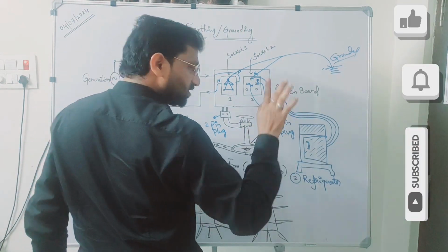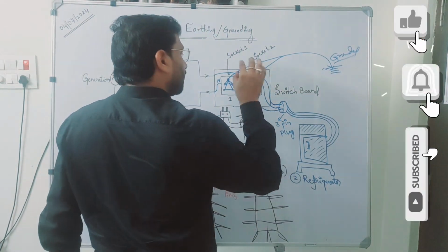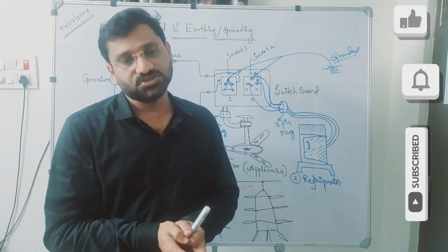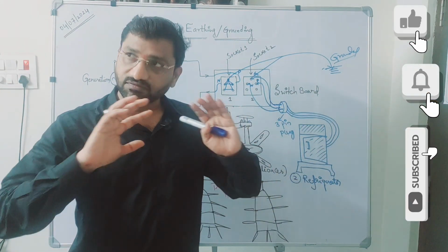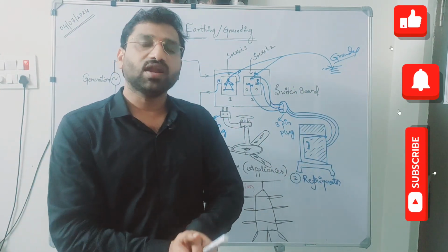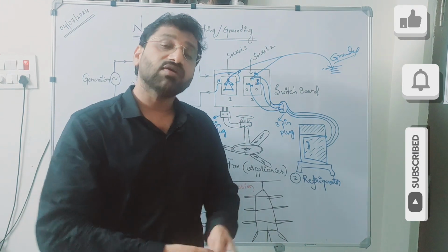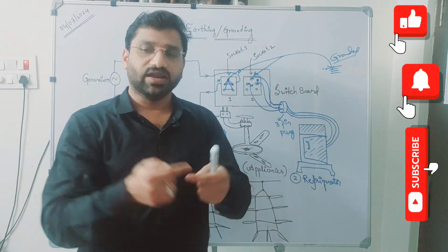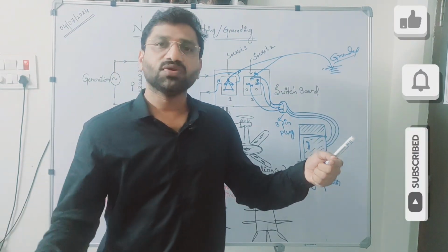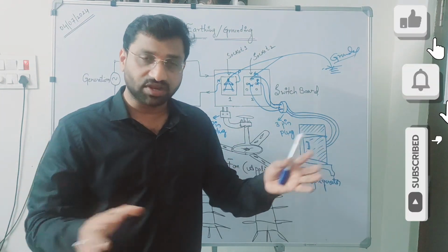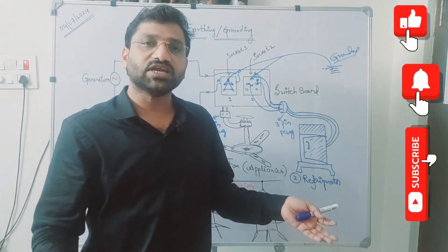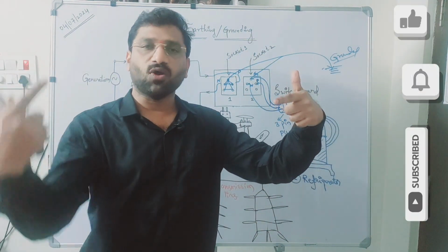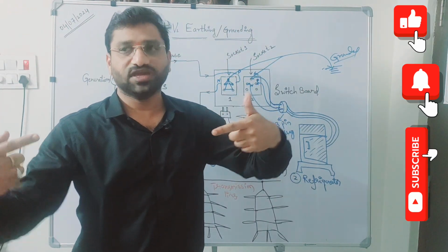That is the reason a 3-pin plug is always suggested. The ground wire is nothing but a safety precautionary item in the electrical system. Every part of the switchboard should be connected to the ground, and every part of the appliance should have the ground pin. Only then are these two synchronized, and if there is a short circuit in any part of the system and the appliance body gets charge over the surface, that charge can be diverted to the ground with these two connections: one is the ground pin of the appliance, and the other is the ground wire of the system in the house.